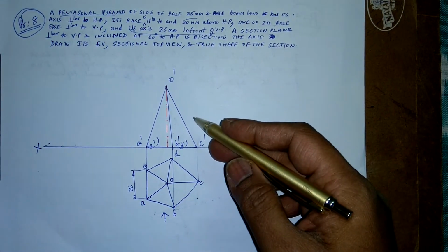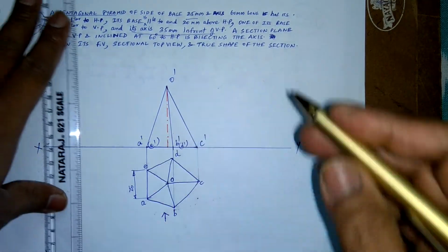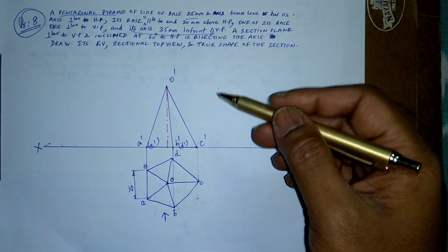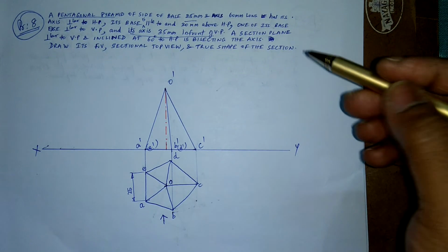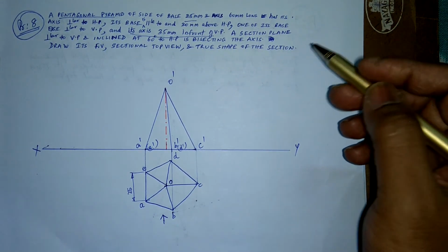I projected the height, whatever the height of this one is. I'll have you do the dimensioning later. So this is the basic projection, front view and top view of the thing, like solid problems. But now I have to go ahead and do the sections of this thing.